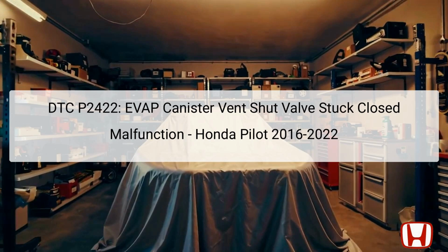The EVAP vent shut valve is generally located near the EVAP canister, typically situated under the vehicle, near the rear area of the fuel tank. Addressing this issue promptly is critical for maintaining emission standards and ensuring that the vehicle operates efficiently.